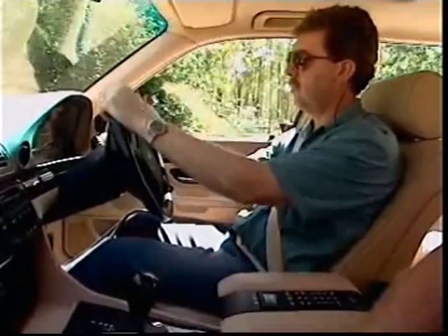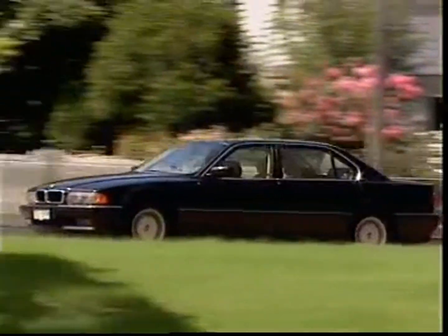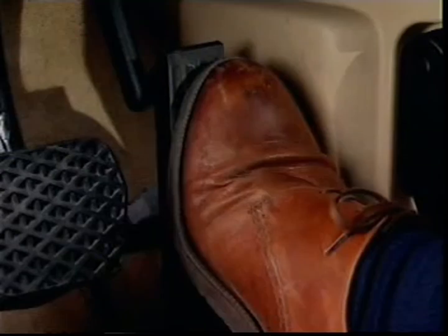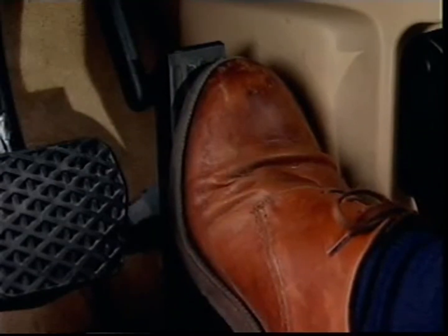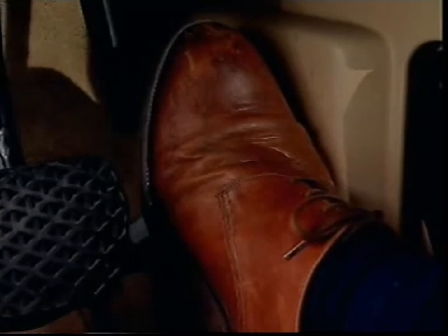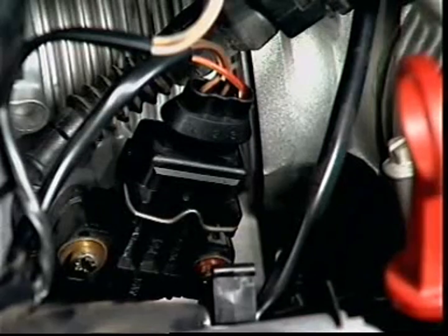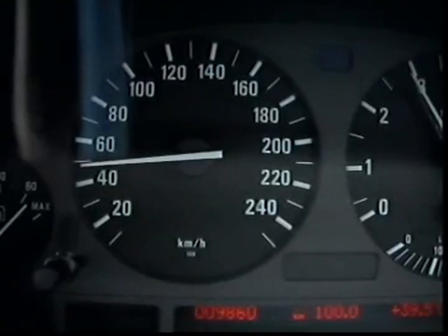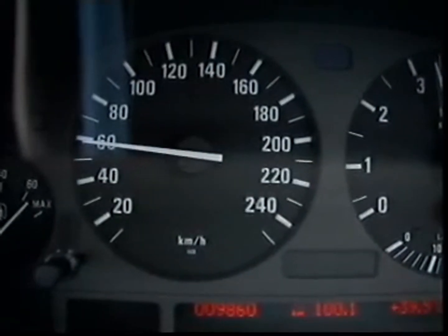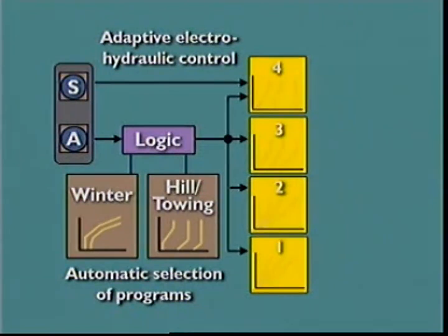Accelerator pedal movement can be evaluated when moving the vehicle away from rest and during regular driving. The length and frequency of kickdown periods can be evaluated, and the speed of accelerator pedal movement, or kick speed. This data from a throttle position sensor, together with vehicle road speed, can identify driving style. One of four shift programs can then be initiated.